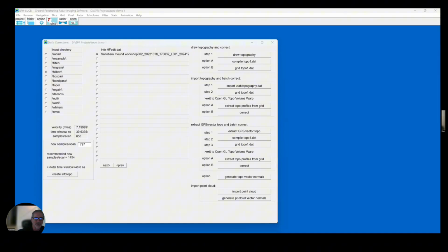So what we do is we show the data on relative, and we let each map be independently colorized from the rest. And are we justified to do that? I think so, yes, because imagine if you have one area where you have a reflection at subsurface depth, and another area you don't have that same layer. Well, the signal that goes below that next layer has already been reduced. And you may have a similar layer that's down below, but it may be weaker over here than it might be over here. And so normally we want to use everything in the relative normalization. And what we do is for each map independently, we colorize each map independently, and then we interpolate that.